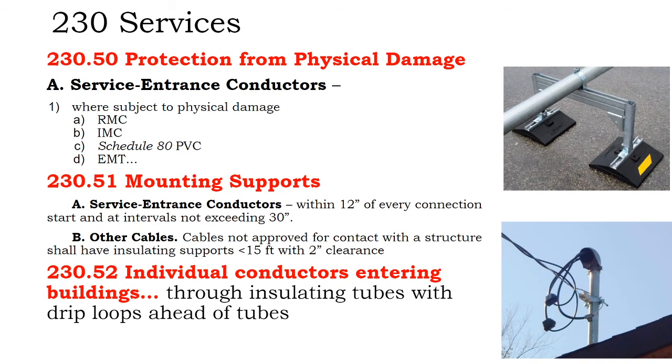Service entrance conductors should be protected from physical damage, and so there's more robust EMT to protect from that. Service entrance conductors do not need to be in conduit. They're outside a conduit, wet, outdoor rated, and they can just kind of dangle before going into your house. But if they're subject to physical damage, then they need to be in conduit.